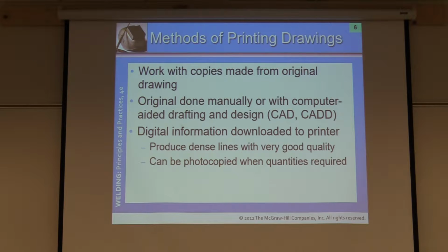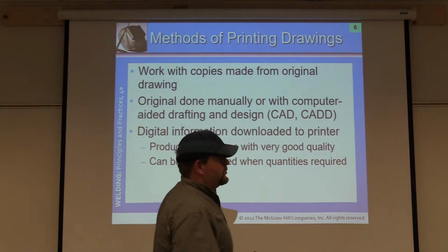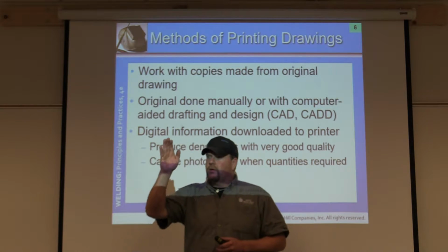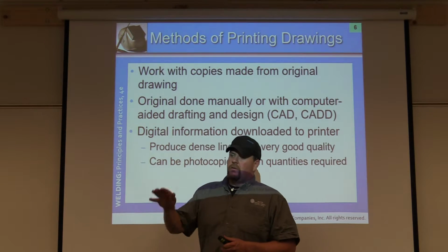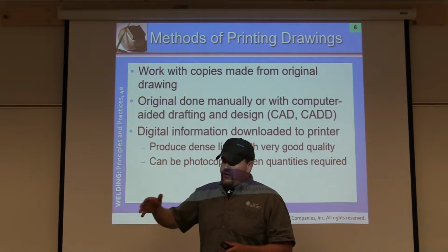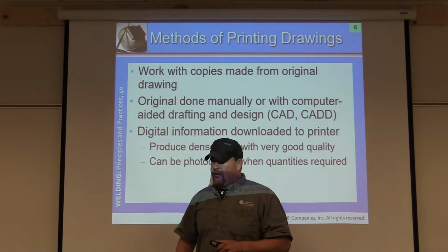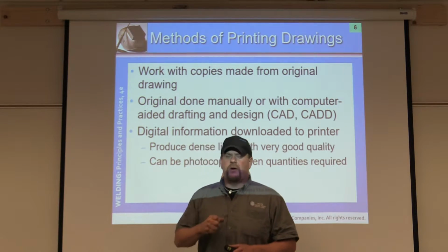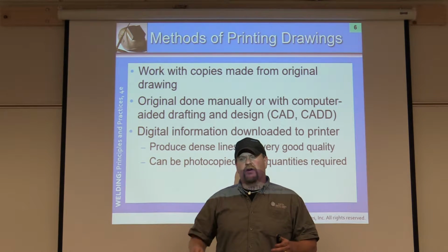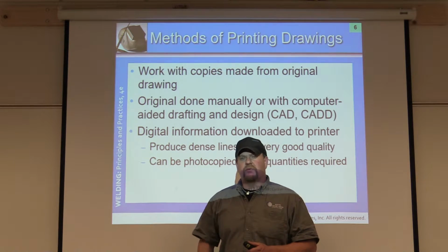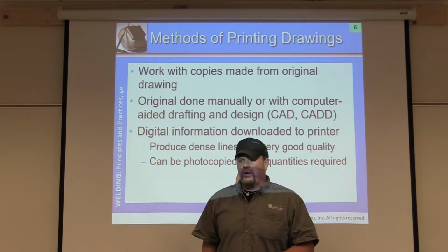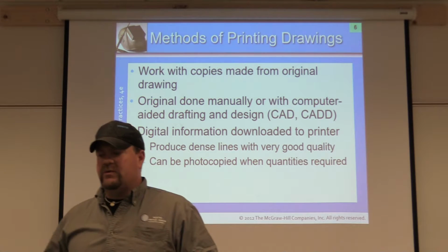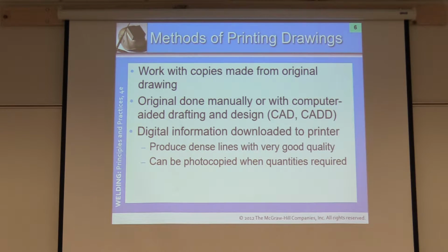Sometimes you're going to get out there and you're just going to get a plain old shop print. Or you may have to create your own just to make sure that it goes right, or pull your material supplies real quick. Say, okay, I'm going to come down here, go here and there. Rough estimate of material. I can do that in 20 feet, 4 90-degree fittings, but I'm going to need a drip leg T here. I need a valve here, check valve there, and you're going to draw yourself an isometric shop view a lot of times before you go into the field or before you go to the job. If you don't have a print already, it's important to know and use to keep things straight in your mind as well.